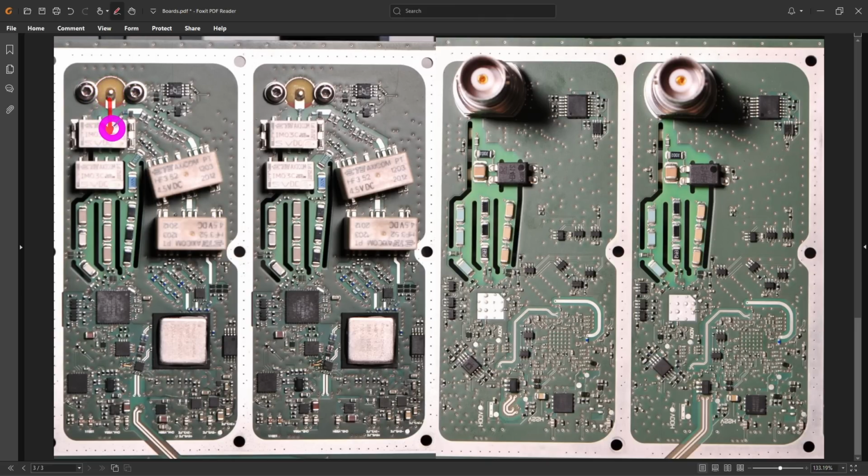That relay can have several uses and advantages. First of all, it can switch between 50 ohm and high impedance mode. It can also serve as protection in case the 50 ohm path is being overloaded, because the maximum signal there is quite a bit smaller than in high impedance mode, and it can protect your 50 ohm termination that way. It can also be used for switching and calibration paths and so on into the front end. And the two paths look quite different, and on the other side you can come back all the way out, and this is a 50 ohm path almost certainly.